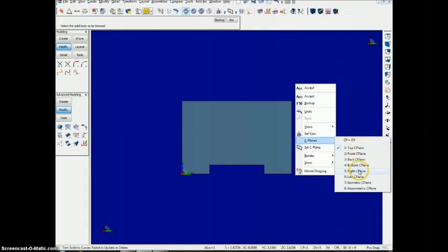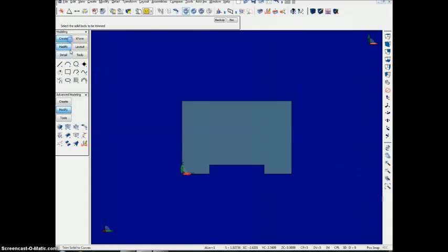So make sure you have the right C-plane and view. Create line parallel distance 0.5. We're going to go 0.5 from the left and right as well as from the top. Modify trim first. We're going to get the trimming curves once again. Trim solid curves. Okay. 3 trimming lines. Accept. Solid body, and to the left again.